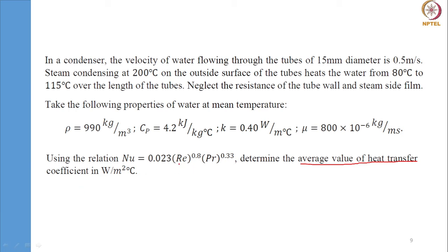First, find out what is Reynolds number for this water. Is it 9281.25? Yeah, that's fine. So one of our friends says that it is around 9281. Reynolds number we know is defined as GD by mu, or you can write it as rho VD by mu.